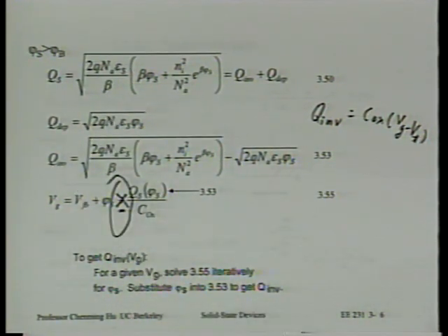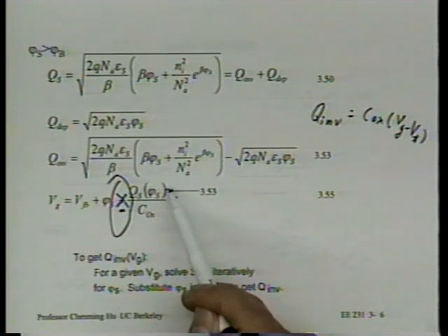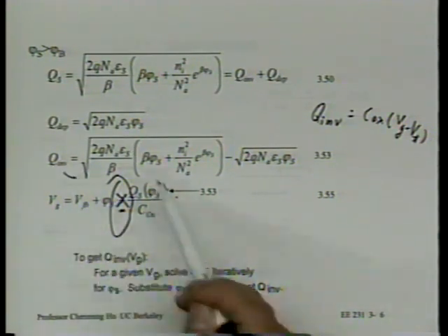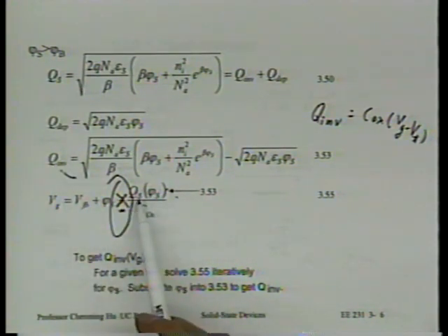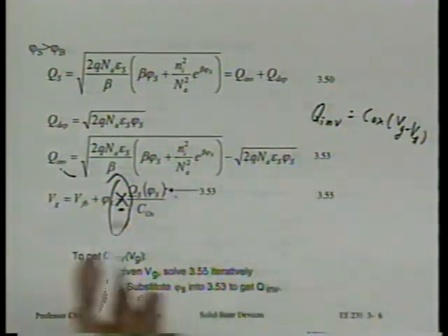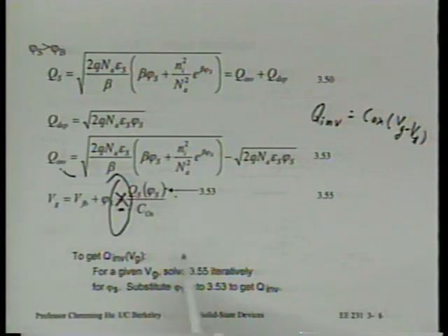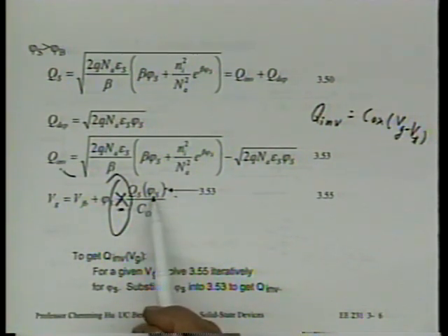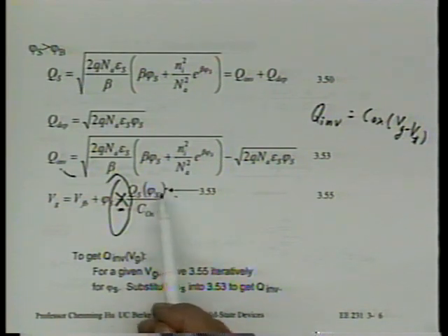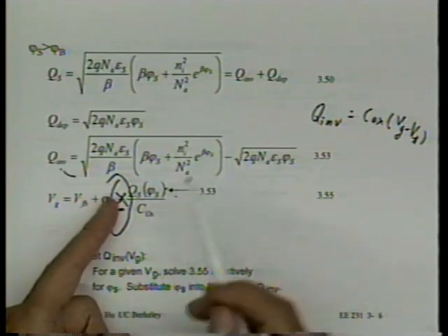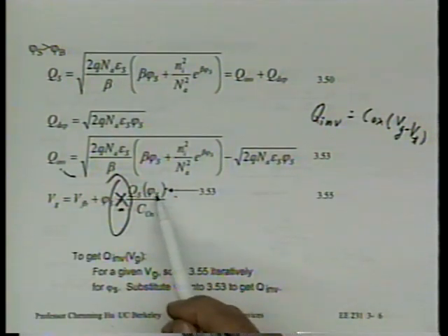I don't know if it's clear or not. We'll solve this equation here. All right? Of course, this term will be this term here. Well, this is only one part of that term. This will involve the full three equation term, right? The three component term, holes and depletion charge and inversion charge can all be included. It's a long expression of phi s involving exponential functions of phi s, right?